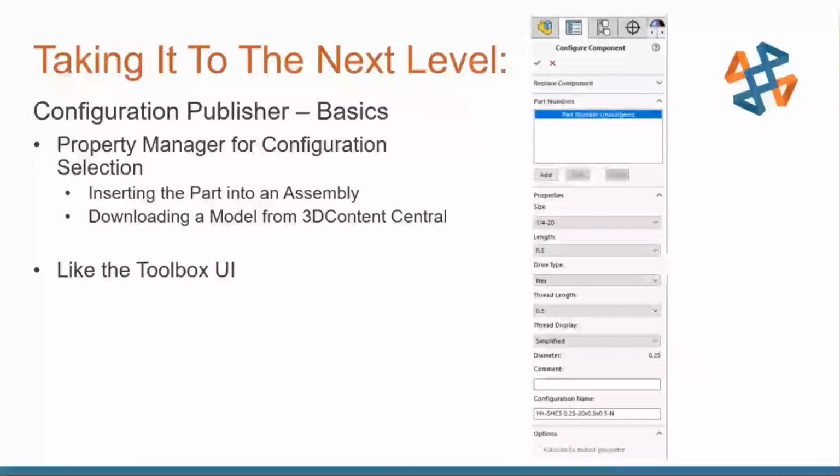But since we're limited on time, I'm going to jump into some other aspects that we can leverage configurations and design tables for, and that is the configuration publisher. So this allows us to control, or I should say build and control, a user interface so another user has an easier time selecting configurations to use in assemblies, for example. Very much like the Toolbox UI that I have a screenshot of there, but we're going to go ahead and build one of these from scratch just so we can see how it works.